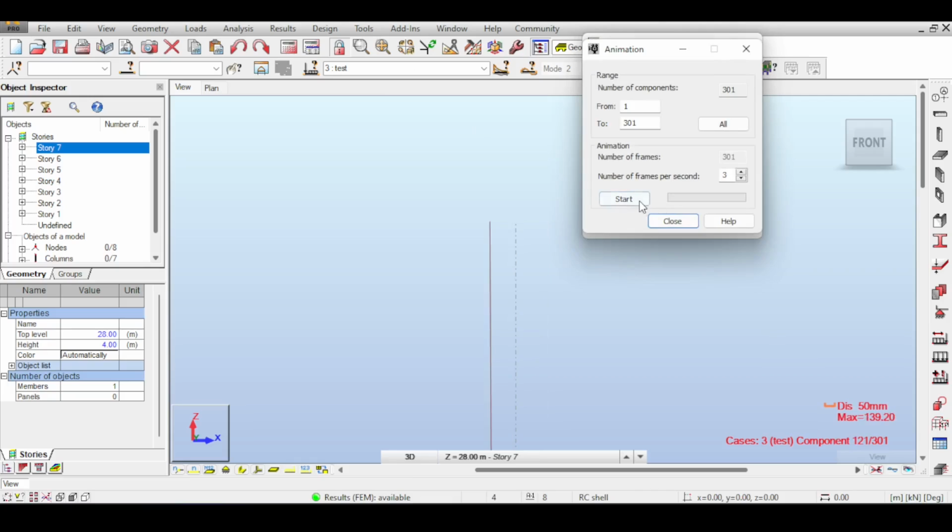Let me just check. I'll just basically start an animation and take a look at that because I want to see if damping is included or not. I personally do not think that damping is there. I cannot see any exponential decay of the motion. Let's see. So from here to here. Yeah, no, it's not decaying. Okay. Yeah, see, I'm holding my cursor intentionally in a certain position, and you can see, look at the deflection; it's still 175 all the time. So no, I don't think there is a damping here.